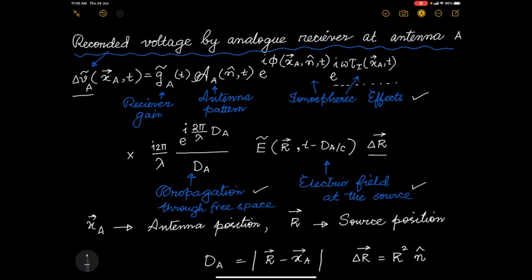If you look at this entire chain, you don't have any mention of frequency anywhere. And that's for a good reason. Because when the signal comes to you, you can actually record the signal as a function of time. This you can do because we are talking about a radio frequency, which is like a few gigahertz. And if the signal is a few gigahertz, you can very well sample it using a computer.